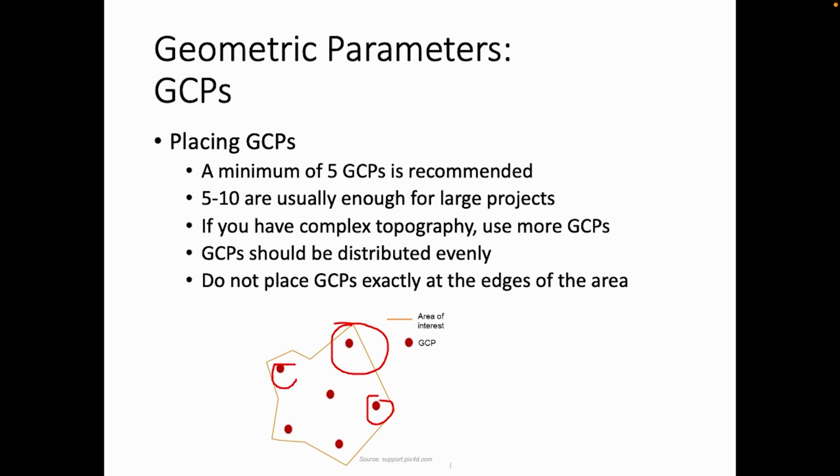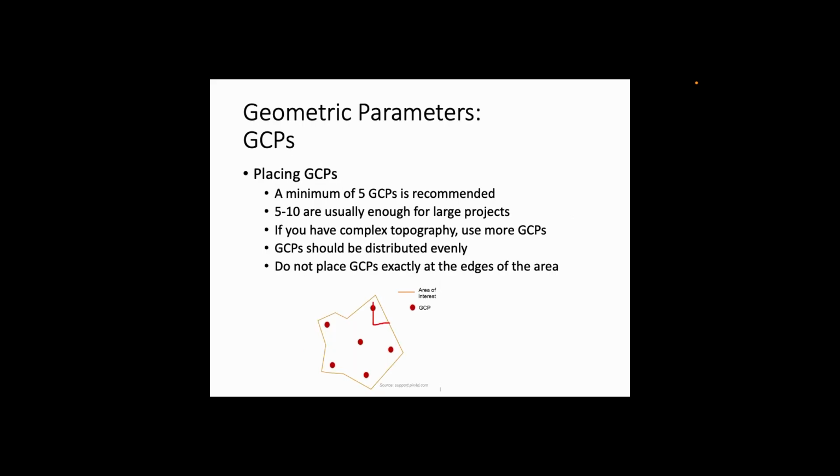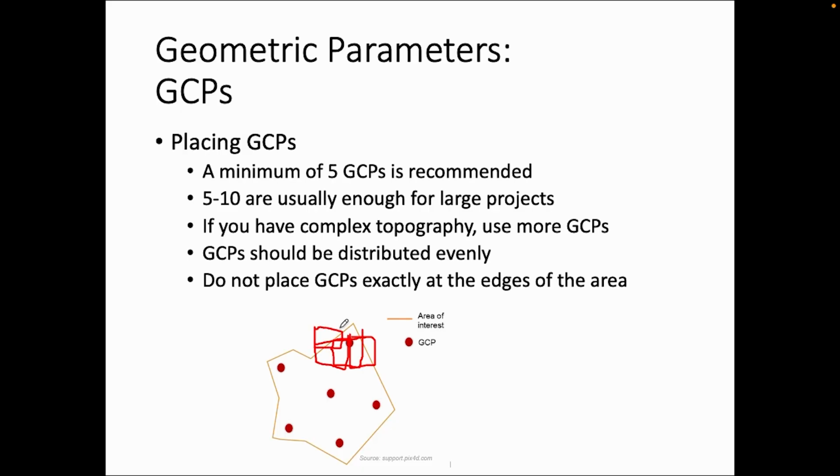On the other hand, if we've got the GCP marked in a bunch of photographs, and let's say we've got a bunch of overlapping photographs now, if I'm overlapping my photographs, now the GCP is showing up in many more than just 1 or 2 photographs. It's showing up in a bunch of photographs because of the amount of overlap that I have, and it's a little bit of ways away from the edge of my study area.